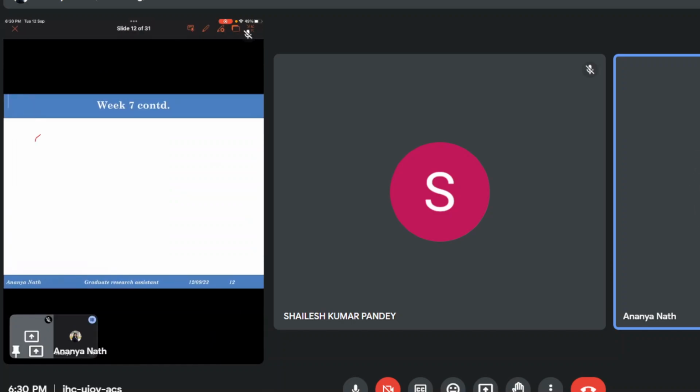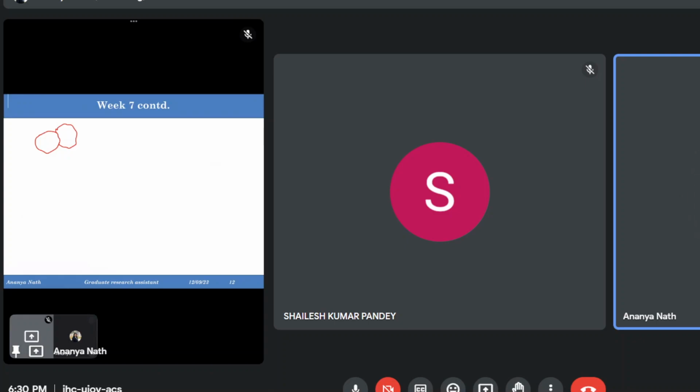So if you have one grain with a lot of dislocations inside it, and somehow bulging takes place at the junction of two grain boundaries, this bulging may give rise to a new strain-free grain. We know that by rearranging, if this is a high dislocation zone, the dislocations arrange themselves and form a new strain-free grain, which will be counted as the low energy zone.